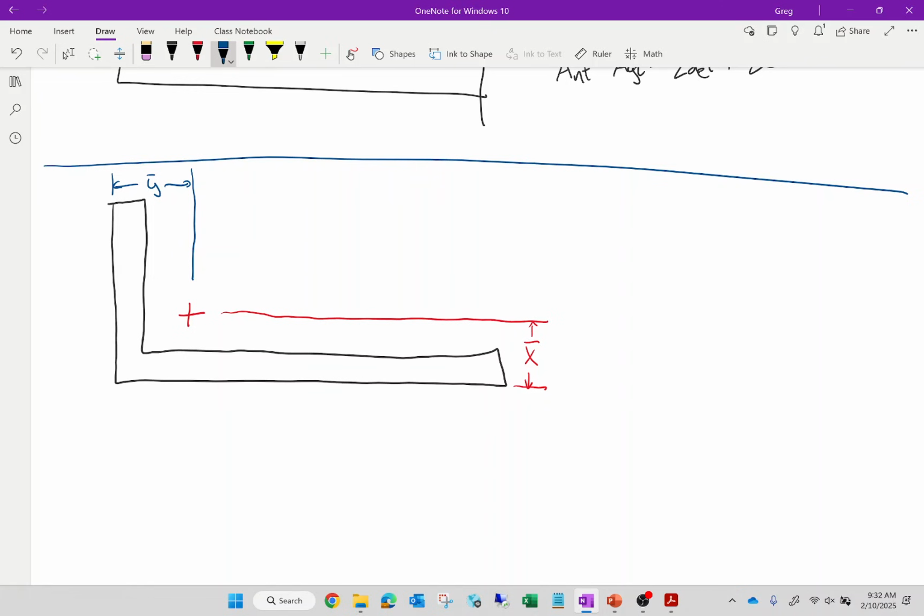But let me also add a dose of reality. If I had an angle like that, where are the bolts going to go through? The long leg, right? Which means which value are you going to use? X bar. By the way, look up an equal leg angle. What's the difference between X bar and Y bar if the legs are equal? They're the same, yeah. So that makes things a little nicer for you.